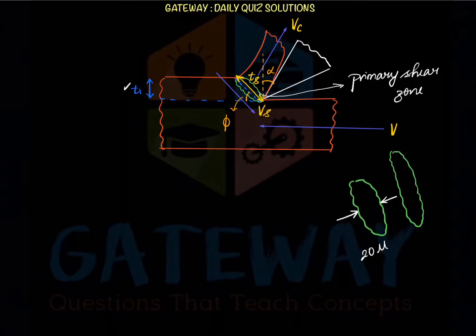See here, initially it will have some primary zone here, and next the shear zone thickness will be reduced, and so on. It will be reduced, and finally it will become a line. And once it is a line, it breaks off. This is the mechanism by which the primary shear zone helps in the cutting, or in breaking the chip. So all this happens in the primary shear zone.